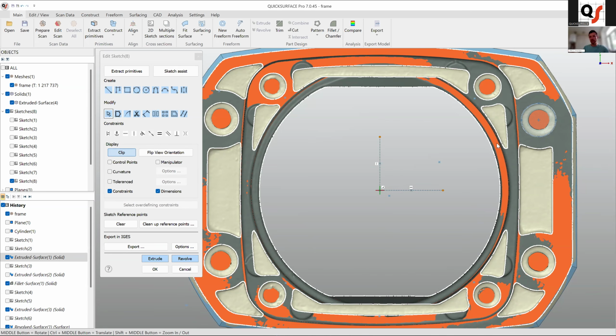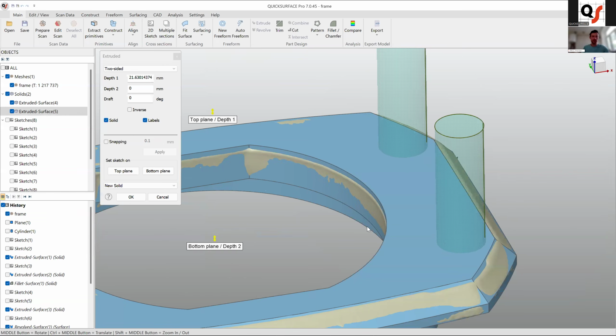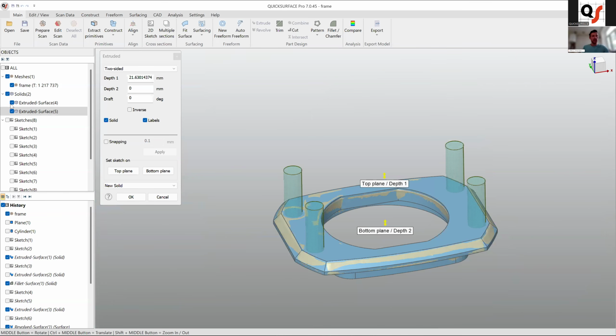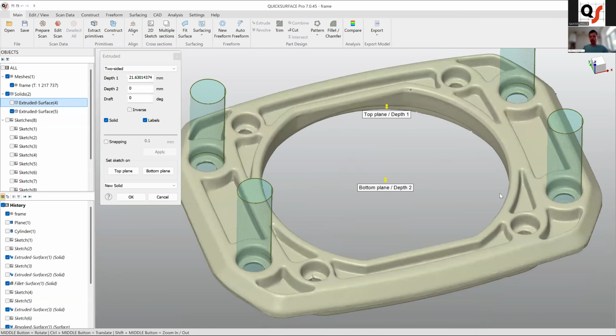You want to create it based just on scan data, so how good is the scan data and how good is the fitment of these mounting points, and you want to follow just the scan data, or you want to create this by logical CAD. It's just personal preference, or probably some requests from your customers. Some customers just want to stick to the scan data because they think the scan data is perfect and the part is perfect. So okay, we can let them do that.